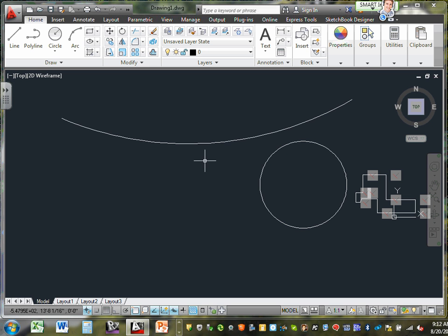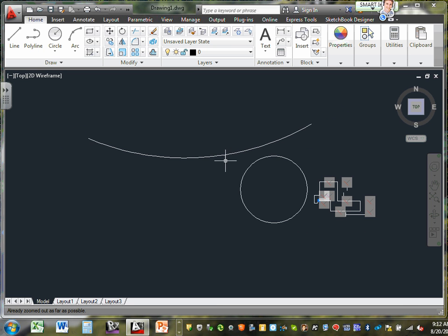If you click on something, you've selected it, which means you can do anything with it right now. If you hit delete, it will be deleted. We'll get into the modification in a second. If you want to do something with an existing drawing, Z enter again, Z enter, E enter, here you go, all my stuff.